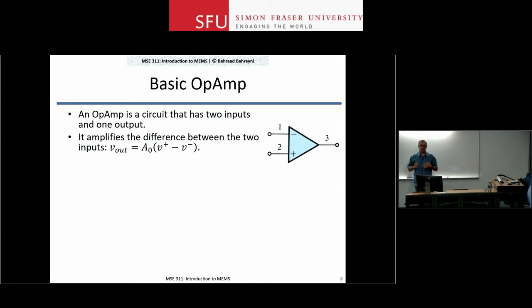But for using transistors, you need to worry about keeping that nonlinear element happy. You want to bias it in the proper operating region. You have to worry about whether you are going to get the gain that you need, the AC-DC coupling between different stages, and all sorts of other issues. In most cases, we can do the same task with an op-amp without any sacrifice in performance if you're a bit careful. And in most situations, the circuit is going to be simpler.